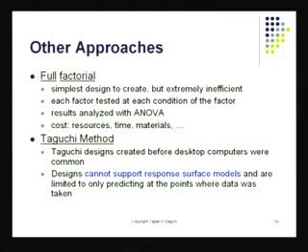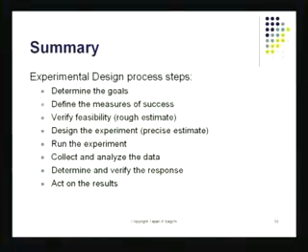For example, the full factorial method is there, like I told you earlier. The results of the full factorial trial are basically analyzed using ANOVA. Taguchi methods, on the other hand, lead to fairly simple, straightforward calculations. But the Taguchi approach to conducting experiments cannot really figure out, many times, interaction effects between 2 or 3 factors, because most of these turn out to be partial factorial designs.